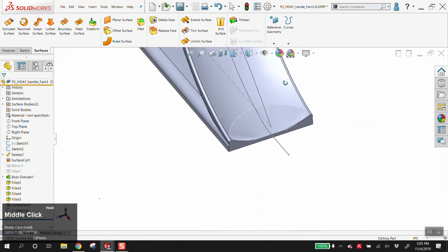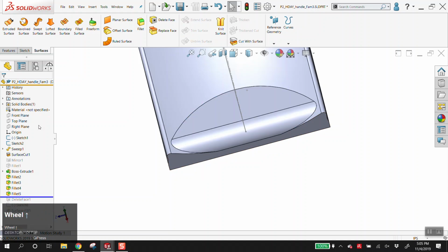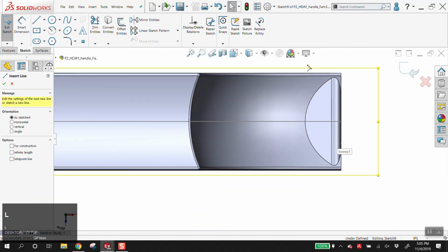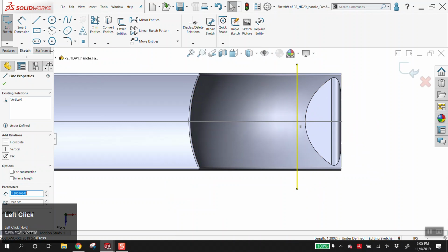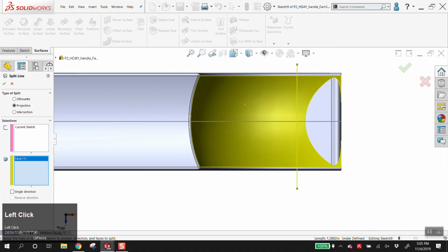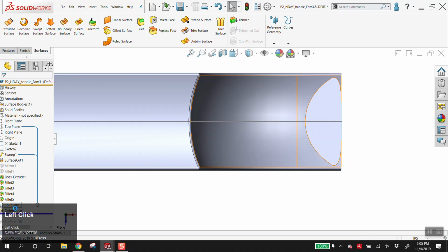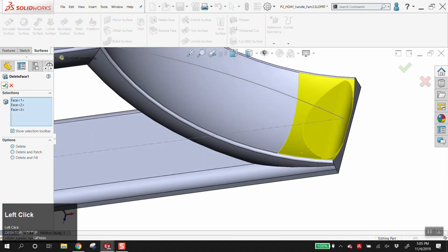Anyway. Could you just cut, like you deleted that area, could you just make a square and delete it? You could. That's also totally done sometimes. From a top view, to your point, you could make a sketch across here and split the line along here and here, or just here. Now when you go to delete face, you have more you can delete, so you could also just delete this surface as well.